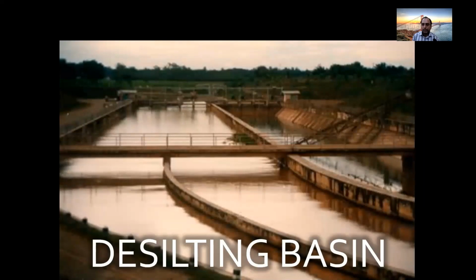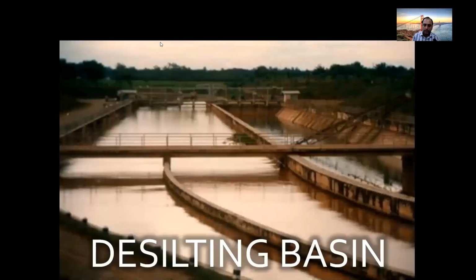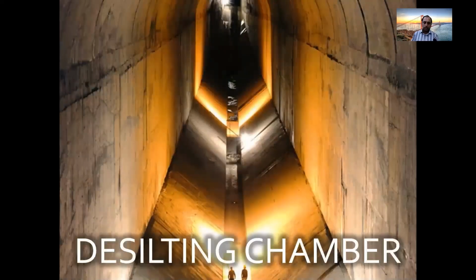Next, desilting basins. Desilting basins or desilting chambers are arrangements which are provided to remove the silt and take it back to the river. This is a desilting chamber. This is a desilting basin. Here, the bottom of this desilting basin is also kind of hopper shaped to capture this silt and take it out from the desilting chamber. And these desilting chambers are very large.